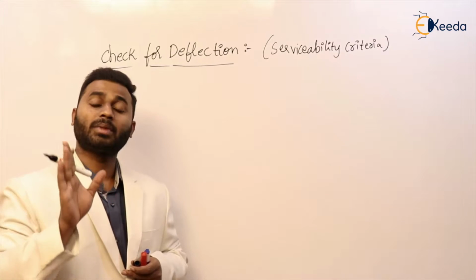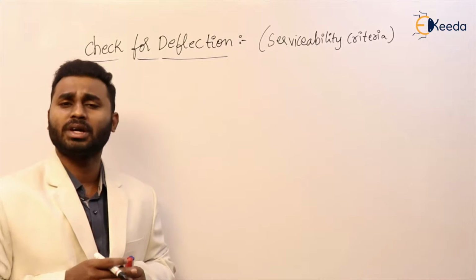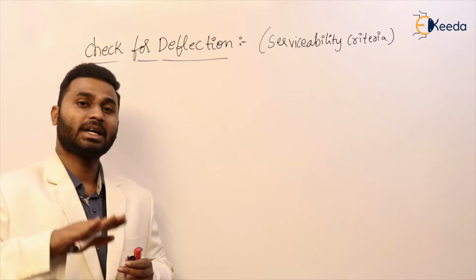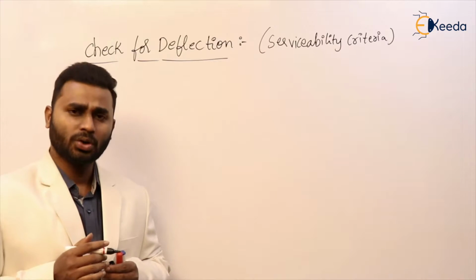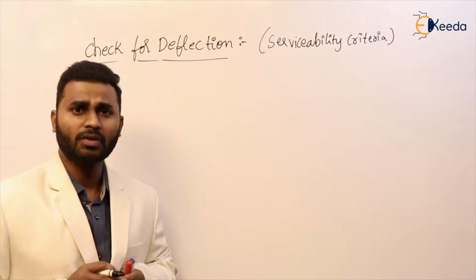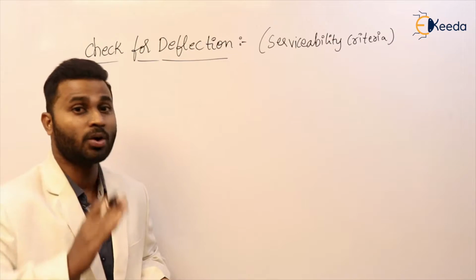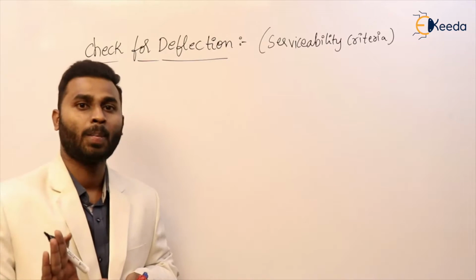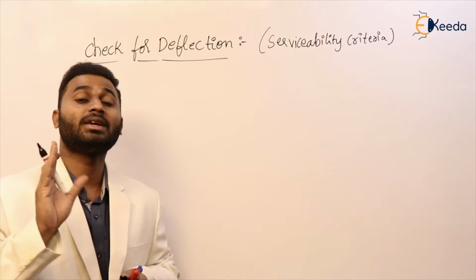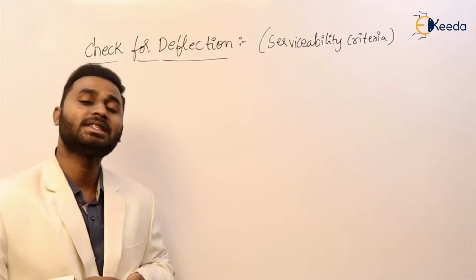It is based on some conditions. First is that it is aesthetically displeasing. For example, you are sitting in some classroom or staying in some house, and assume that some deflections or vibrations occur like this. Are you willing to stay in such a building? Obviously, no. Even though it is strong enough to take the loads coming onto the structure, it is producing excessive deflections or vibrations, which does not give a psychologically good effect. So you are not willing to stay in it. That is aesthetically displeasing.